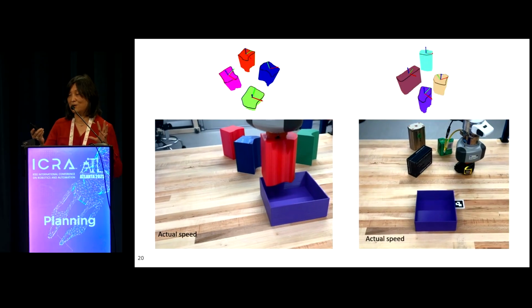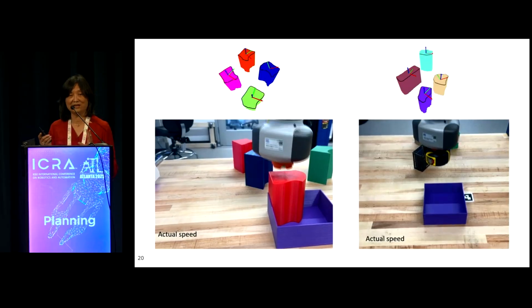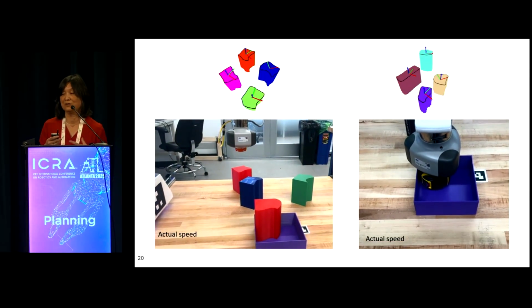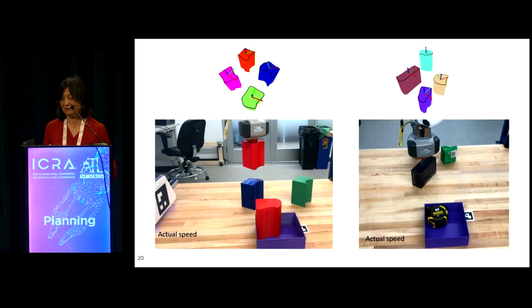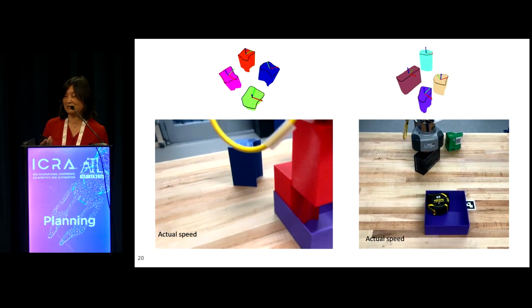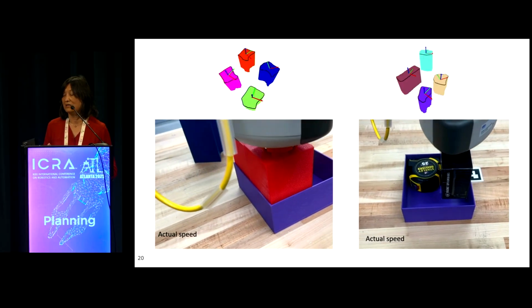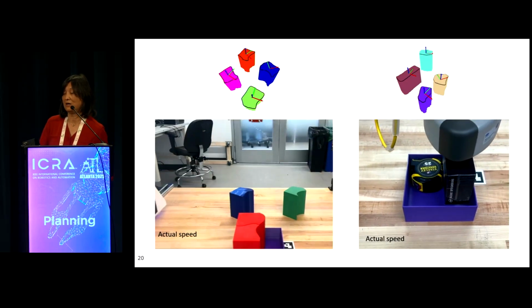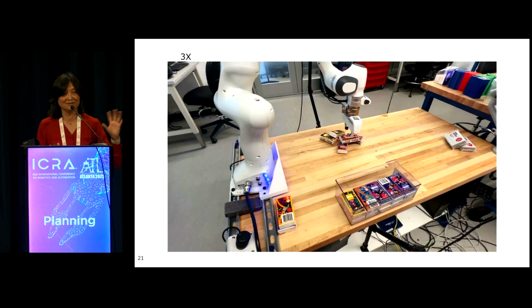So we have these objects the robot has no knowledge about, and it does packing planning to fit the container in the best possible way, maximizing space utilization, and also motion path planning. When it encounters some contact, our contact prediction strategy works, and object insertion can be successful. I tried to fast forward it, but you can believe me that it finishes nicely.